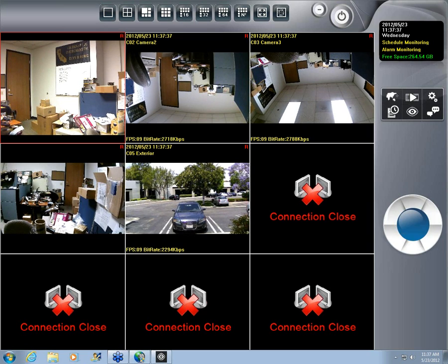Sharuz is asking, when do we plan on doing a Star Force application for outdoors? Because of the cameras, they use a certain CMOS sensor, so it's not possible yet. But we are working on very low light IP cameras in the future. Right now, the best way to use it outside is using external illuminators. The benefit of the cameras that have the ICR is that it does remove its IR cut filter, so it is more sensitive to light now.